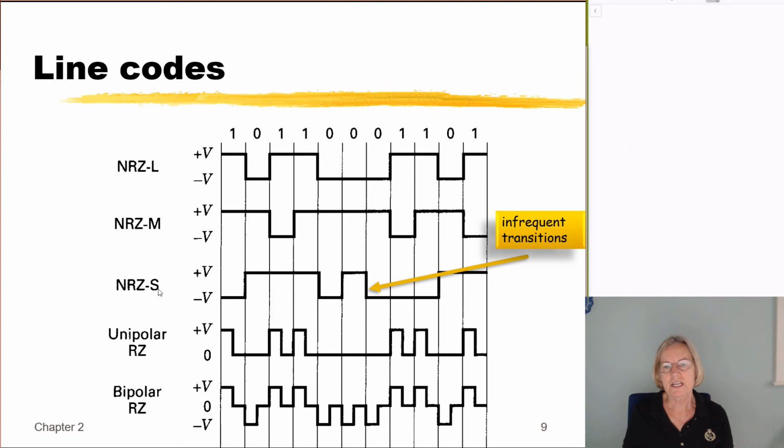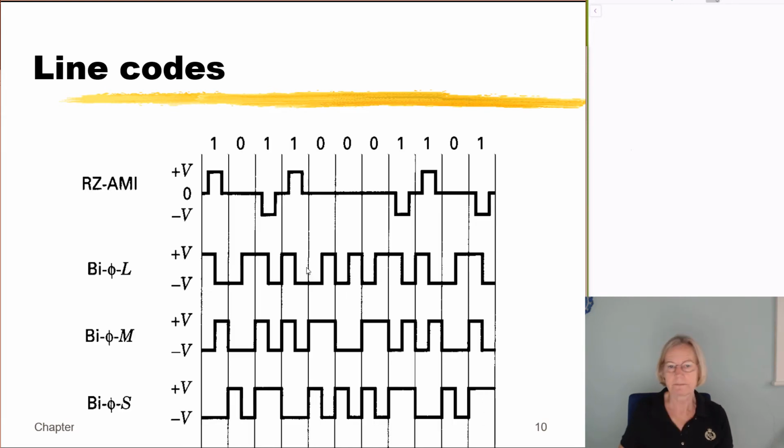Here in the NRZ S, we see that there are not many transitions. I guess same for M. Both of these would be something where we're only toggling on half the time, because only half the bits would involve a toggle. Now in those, there are some other possibilities I can make. In this case, we're looking at different, here is an example of a narrower pulse than what is needed. We have some other choices where we split the bit interval into 2 pieces.